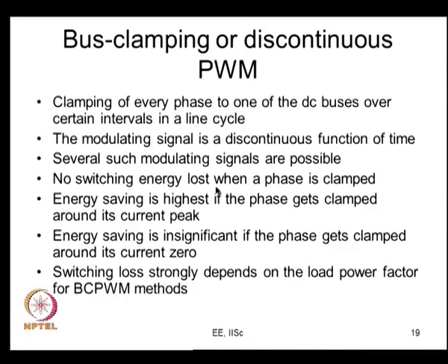So, whenever a phase is clamped, no energy is lost. This has been one of the interesting things about bus clamping PWM. That is also one of the reasons why they are being studied or being used. So, a certain amount of energy is saved, but the energy saved by not switching a phase is highest if the phase is not switched when its current is close to the peak. On the other hand, if a particular phase current is very close to 0 in a particular carrier cycle, and you clamp that phase, the energy saving is very insignificant. So, these are certain things we discussed.